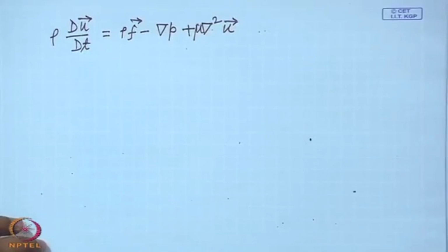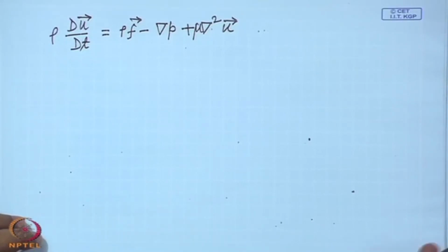And without going for any mathematical proof, I will just state what the difference is between this pressure and the pressure defined in thermodynamics or the fluid static pressure. The fluid static pressure is the same as the thermodynamical pressure, because when the fluid is at rest, it is also in mechanical and thermal equilibrium, which is assumed in thermodynamics.